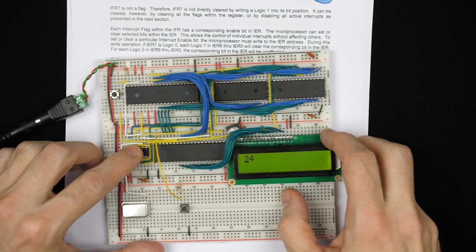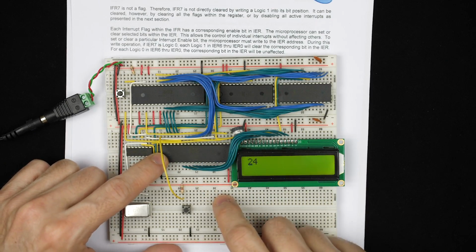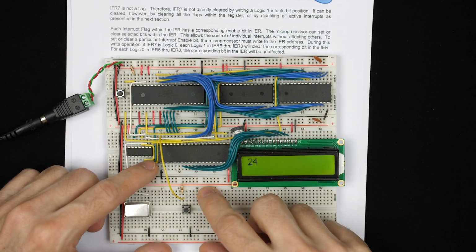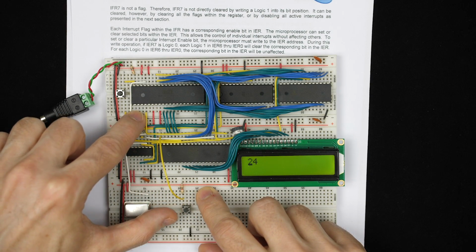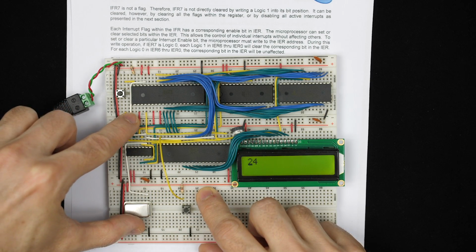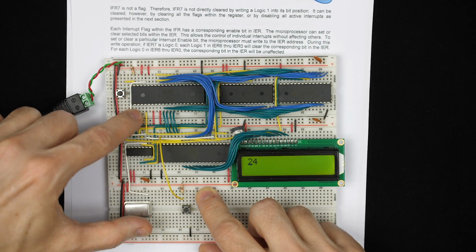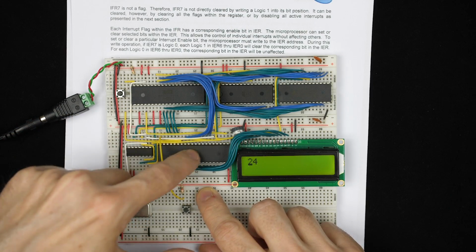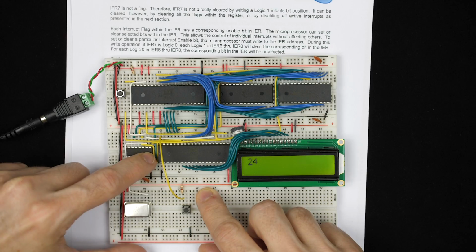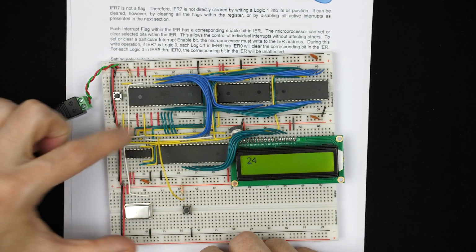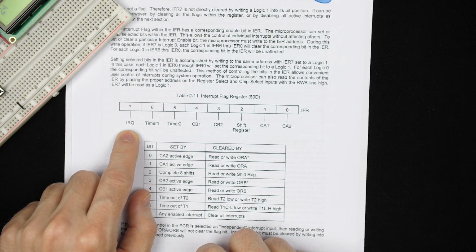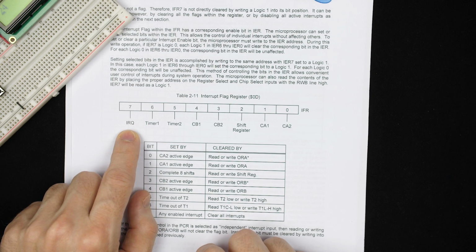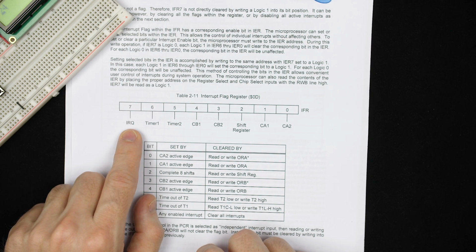So a couple of scenarios. One scenario would be if we have multiple 6522s, we could have many inputs coming in and other things going on. And instead of having a single connection like we do here going into the interrupt request line, we could have these ANDed together in some way so that the single interrupt request for the processor could be triggered by any of a number of these 6522 chips. And in that case, we'd need to read the interrupt flag register from each of them to figure out which one caused the interrupt. And that's where this IRQ bit at the top is very useful because you can actually do that bit compare operator that I talked about, and that'll load this top bit into one of the processor flags. And so you very quickly figure out where the interrupt came from.